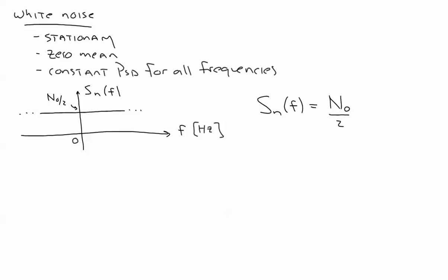All right, now this power spectral density model that is constant for all frequencies from minus infinity to plus infinity is not exactly physical. It would take infinite power to create such a white noise process. But the white noise model is good if the noise is white, at least over the bandwidth of the message or filter that we might be interested in characterizing.